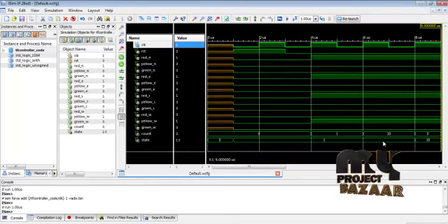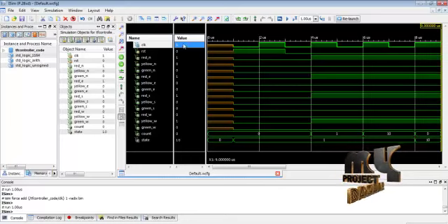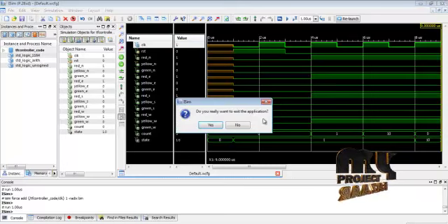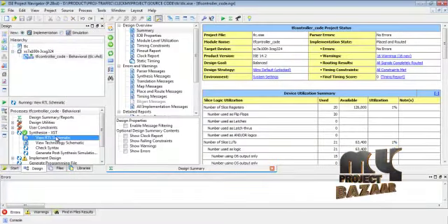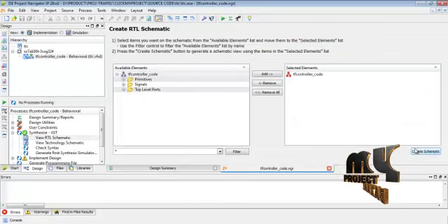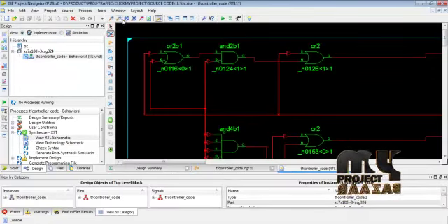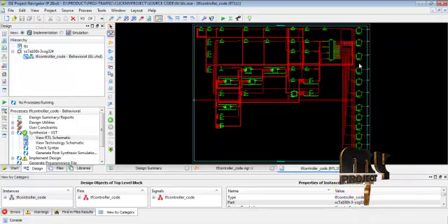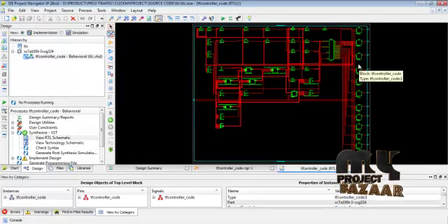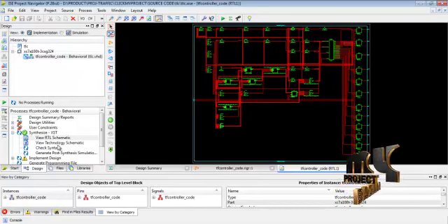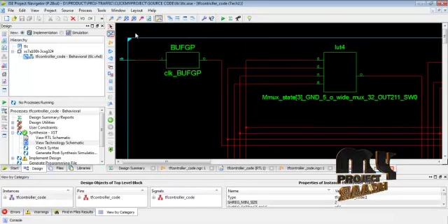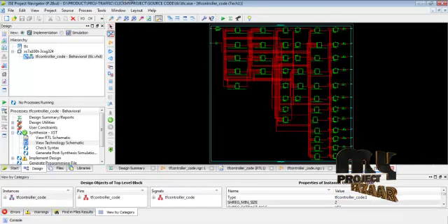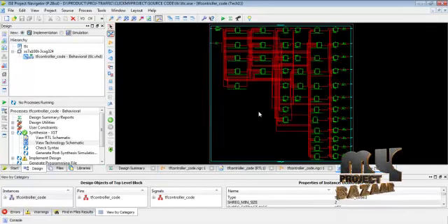These results change the overall architecture results based on our LED functions using the traffic light controller architecture, and we select the implementation process. Then we see the view RTL process. This RTL diagram is mainly used to show the logical blocks, a register transfer level diagrammatic representation. Then we go to the view technology diagram. This technology diagram mainly shows the lookup table functions, input and output, and then the buffer position in the overall IC function.